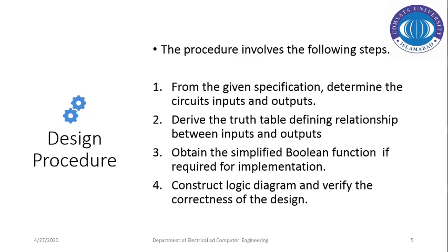Now the most important thing is how we're going to verify the correctness of the design. There are several ways to verify it. Either the correctness of the design can be verified from simulations. We have some simulation software in which we implement the design and verify it, and those sorts of simulations are known as functional simulations that are used to verify the functionality of the design.